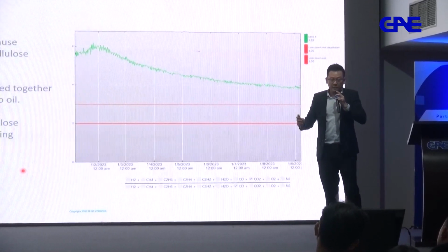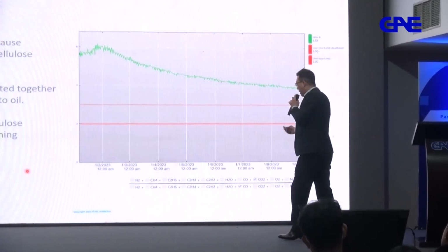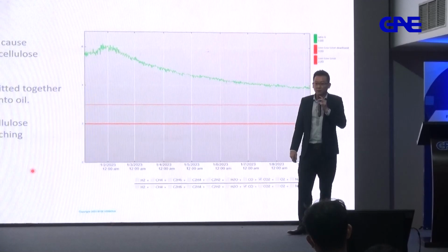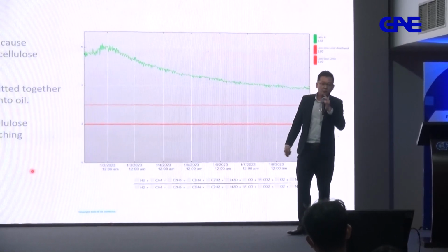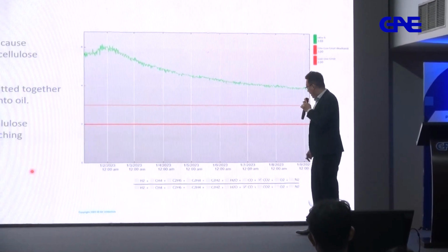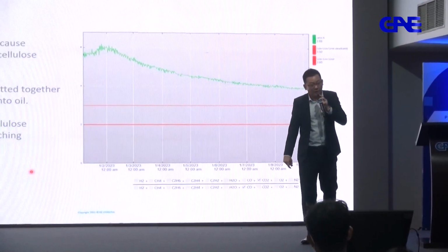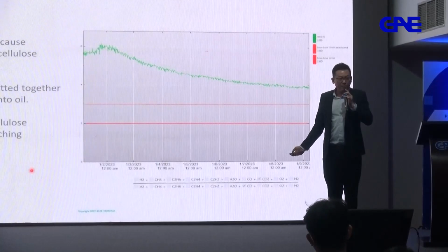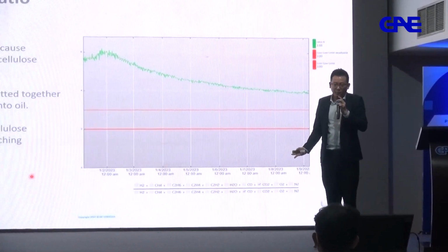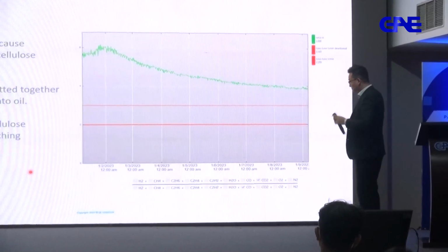You can't just come and tell me, hey, Brian, the carbon dioxide ratio is 5, it looks good to me, there's no insulation issue, there's nothing wrong with the transformer. But when I take a look at it, you're having 25,000 ppm of carbon dioxide, 5,000 ppm of carbon monoxide. It can't be that nothing is wrong with your transformer.